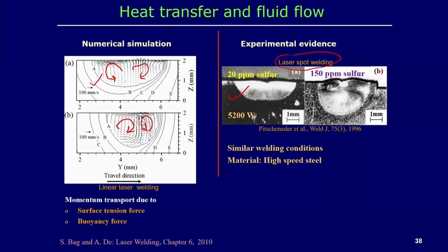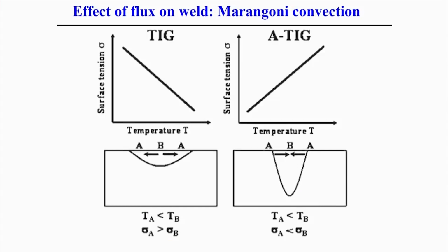But this kind of phenomenon is not possible to capture when you do a simple heat conduction analysis in the welding process. So, here is the importance of considering material flow in weld pool simulation, that means the temperature field as well as the fluid flow field in the fusion welding process. We have done some experiments also, and we can see in the earlier case of laser welding that the surface active elements are present within the material itself.